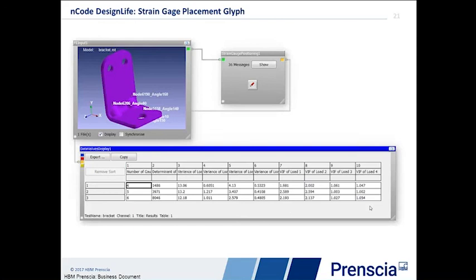But what they're really useful for is, again, we're trying to find unique combinations of strain gauge responses for each load case. And what these are giving me is an estimate of whether two load cases are generating very similar strain responses.